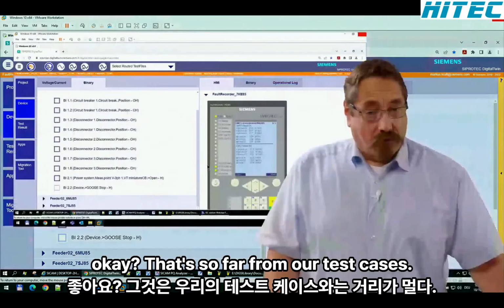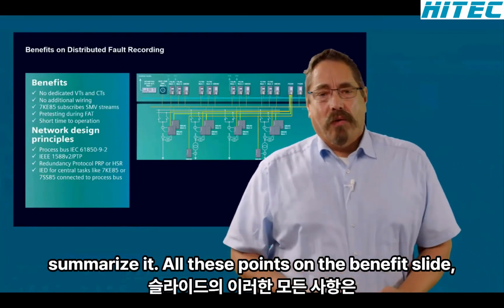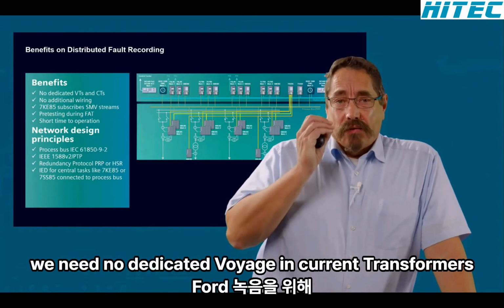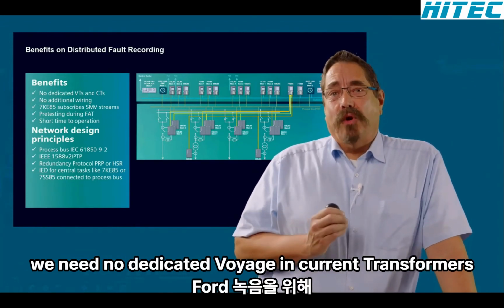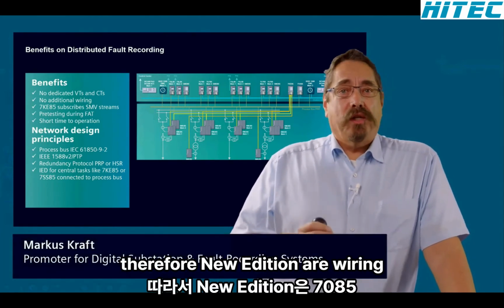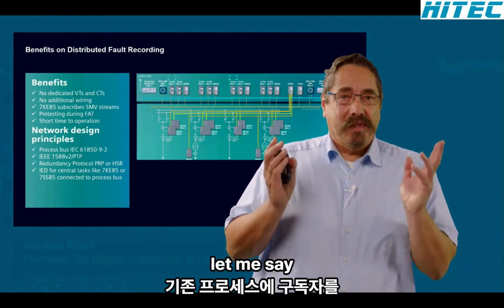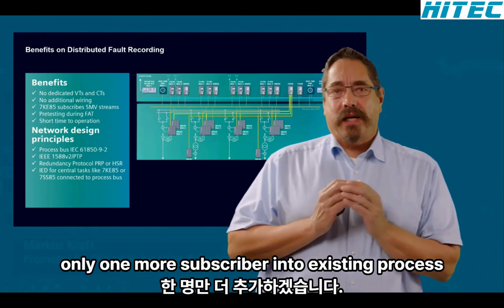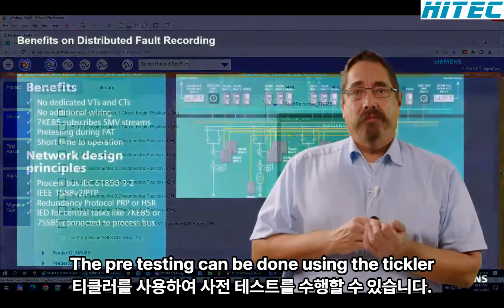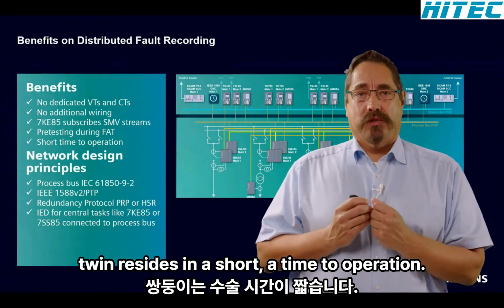That's so far from our test cases. Let me now summarize all these points on the benefit slide. We need no dedicated voltage and current transformers for the fault recording, therefore no additional wiring, because the 7KE85 is only one more subscriber in the existing process bus network. The pre-testing can be done using the digital twin, which results in a shorter time to operation.